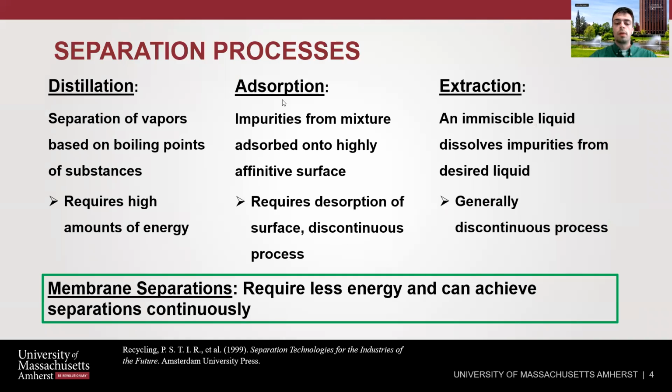Impurities in a mixture deposit into a highly affinitive surface, while the rest of the mixture is not attracted and flows on. The downside to this process is that those impurities have to be removed from that surface, so it's usually discontinuous and requires a desorbing process.